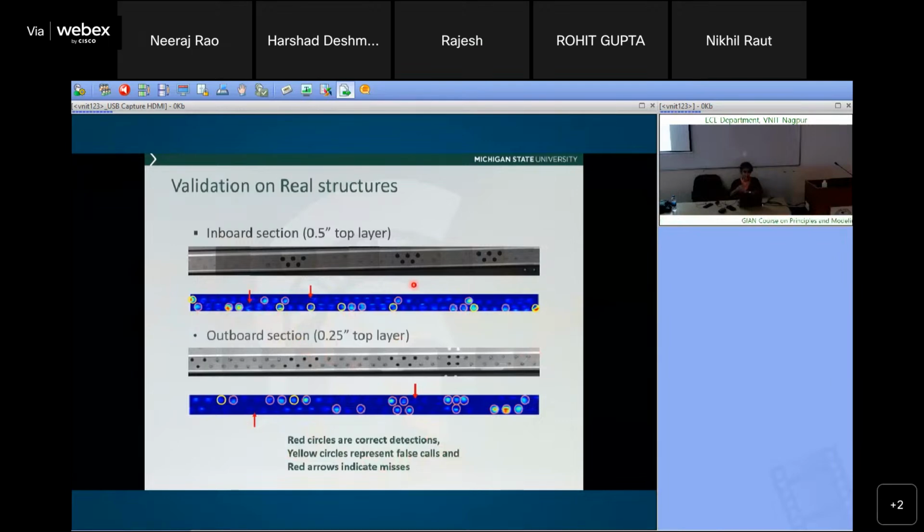These misses are because we fixed the threshold values that we were going to use based on our lab sample. If you have a calibration sample of the actual material, we can probably make the performance better. Also, we are using the same threshold whether it is steel or aluminum, and because of that, we may be missing some of the aluminum rivet defects.